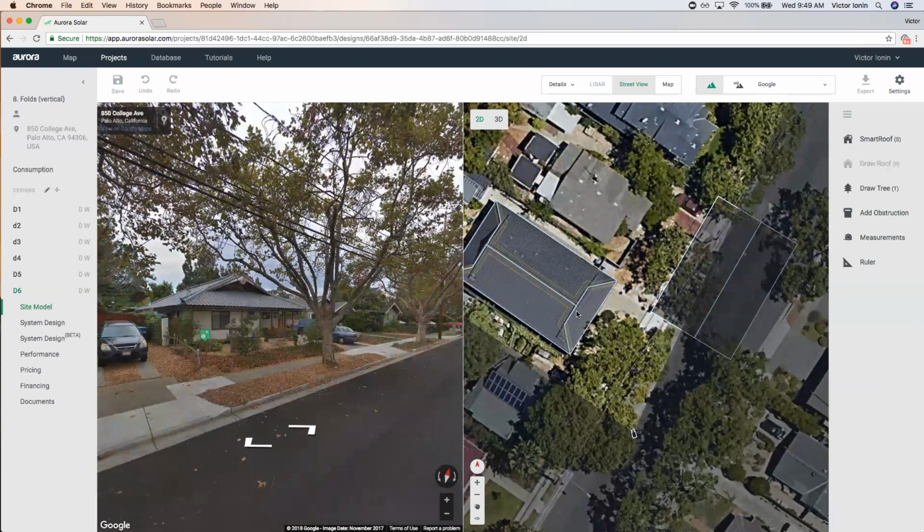And then when you start placing your points, it's going to be able to triangulate what the tilt is based off the distance from the camera view. If you upload your own image, Street View still needs to be available, and it's really important that you scale your image correctly and place it in the right spot. So it's going to be a lot more difficult to do it that way. I do recommend using Google Street View.